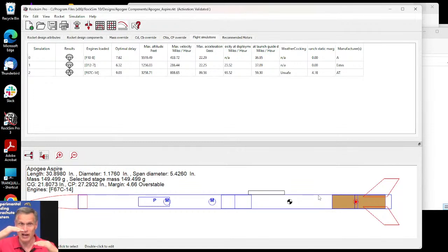But if you have it recessed inside of a tube, it messes that up. And so now, instead of increasing the speed as it's coming out of the nozzle, now you're actually decreasing the speed, and so you're losing thrust. And so the Krushnic effect is you lose thrust if you recess the motor inside of the tube of the rocket, like we're showing here.